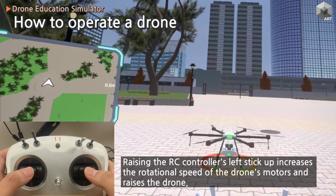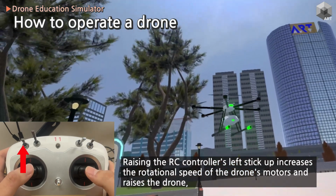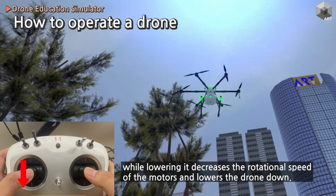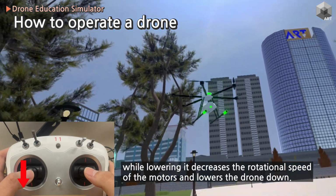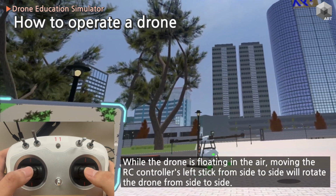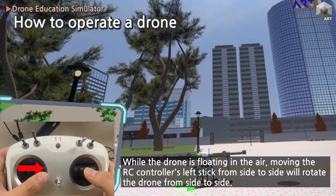Raising the RC controller's left stick up increases the rotational speed of the drone's motors and raises the drone, while lowering it decreases the rotational speed of the motors and lowers the drone down. While the drone is floating in the air, moving the RC controller's left stick from side to side will rotate the drone from side to side.